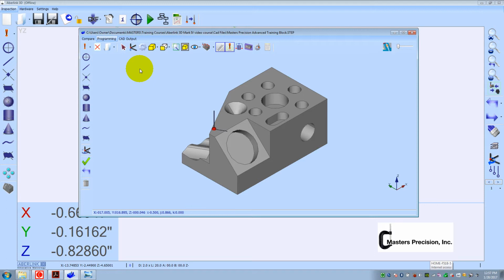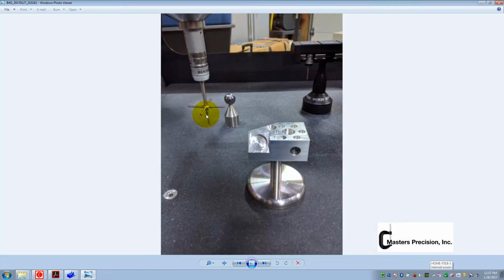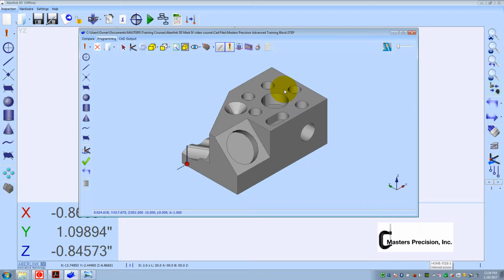I want the probe in the Z minus. I almost screwed up there. So now the stylus is pointing down. It's the bottom stylus of the star. It's that one right there. Before I had that one chosen, which is why the stem was off. So you want to make sure you got the right probe before you start measuring your plane.